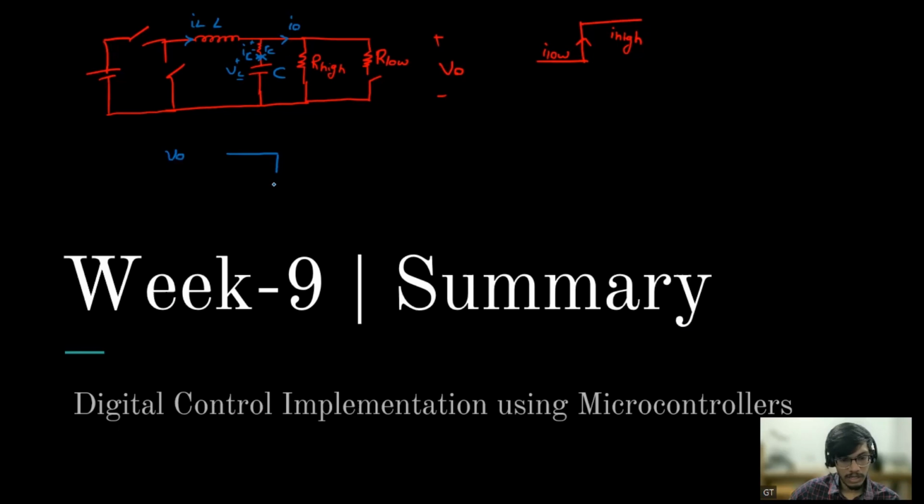So there will be this drop, and then the inductor current will slowly try to charge the capacitor. At that instant the load is demanding high current, which the inductor is not capable of giving at that moment. So the capacitor has given it, because of which there is a voltage drop.